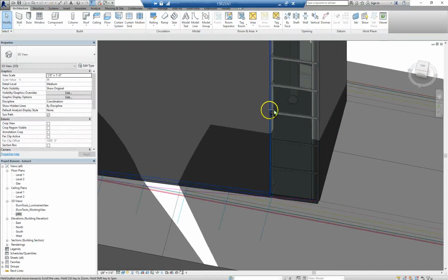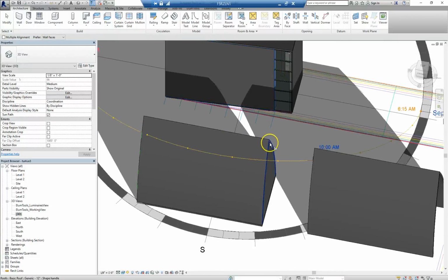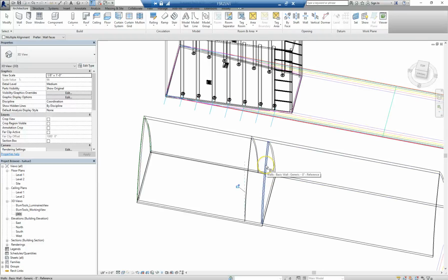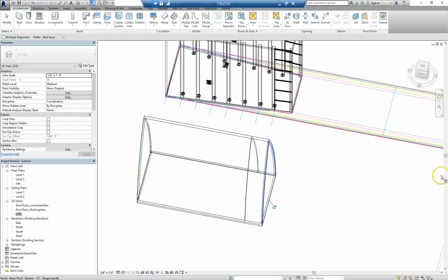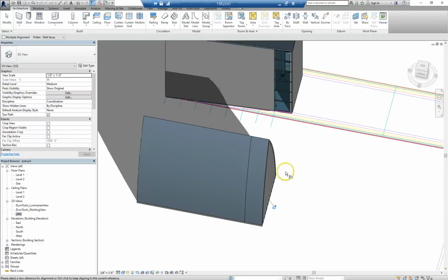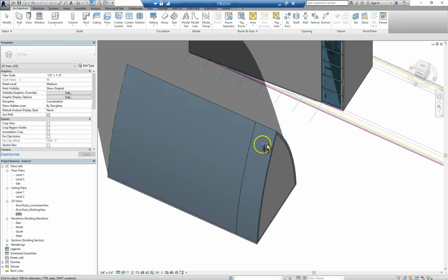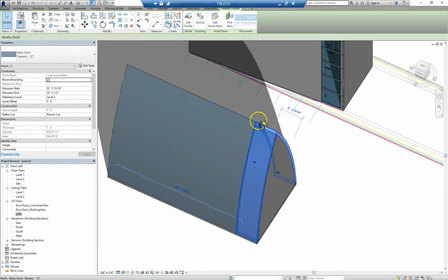Move that whole thing in line up there. Now, align tool again, I type AL. I'm going to click on the side face where the window begins. And you see I'm going to shorten the roof by aligning those two. Now I click align again. And I'm going to bring this to that point. Type WF for wireframe, and I do align again. And align for that end piece. Align it again. Type SD for shaded rendering. And now hit escape and select that roof.